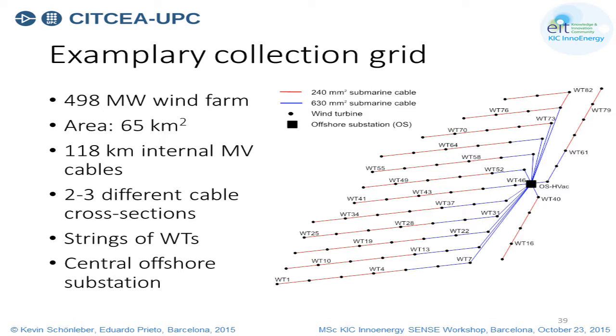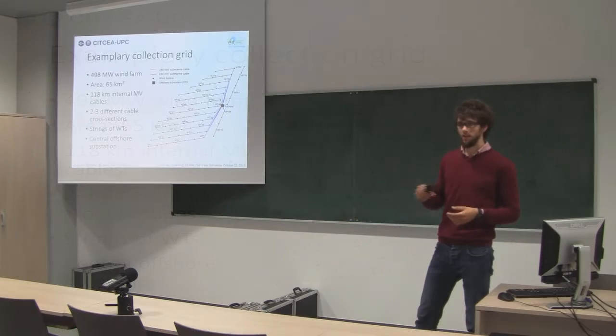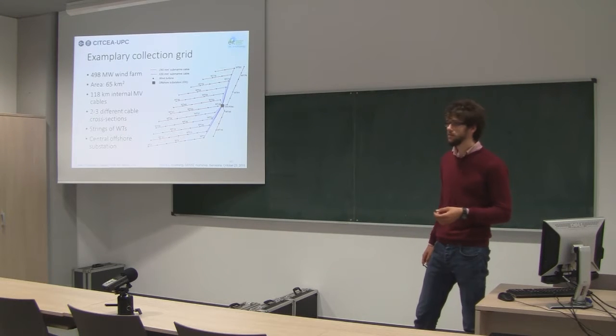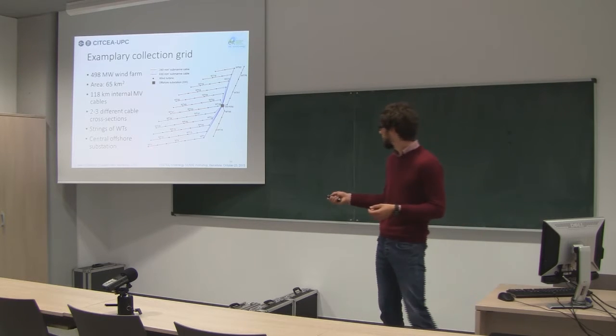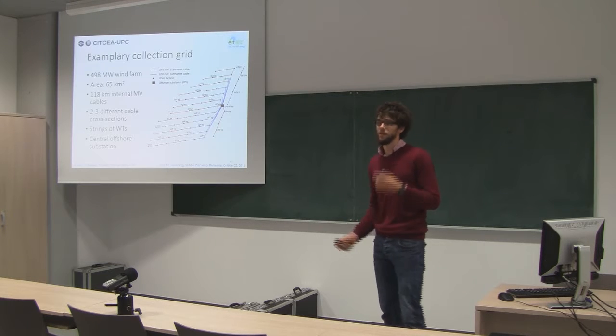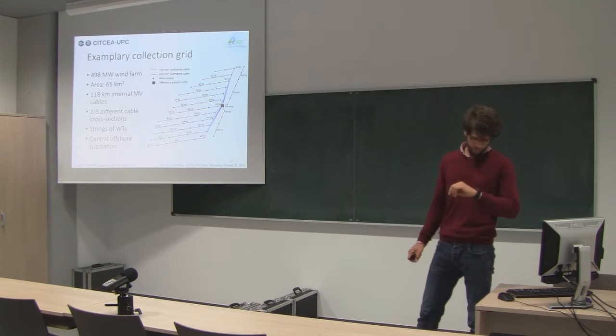So you have here one radial, circular. This one is radial. They were not going for a ring connection, but you can see other projects at the moment which are ring, and I think it's getting more and more common that developers go for ring. So they do a radial and then start the bus. They just close the ring here, so you don't need a lot more cable, and you have this on a small power rating, and then you can still energize the turbine in case of a failure of the ring.